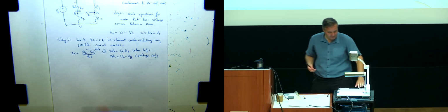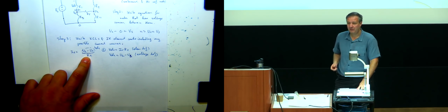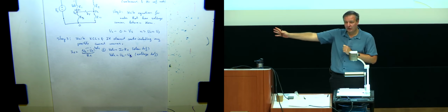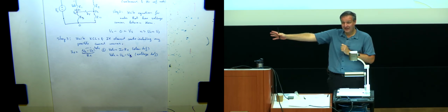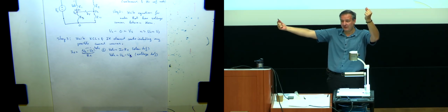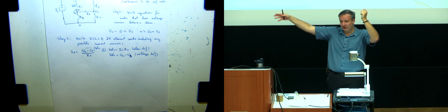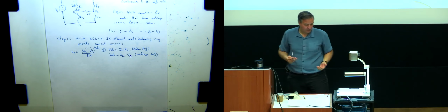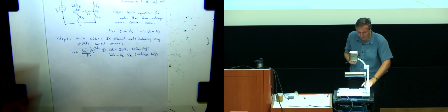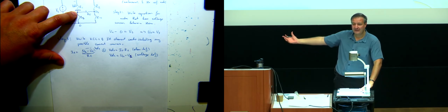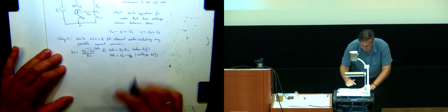Okay, so now this is kind of like a pattern. The current out of the node through the resistor is equal to the potential difference between that node and wherever the other node is over the resistor value. So what I can do now is write KCL for this node U2 right out of these elements. So let's see the magic. So this is the magic.